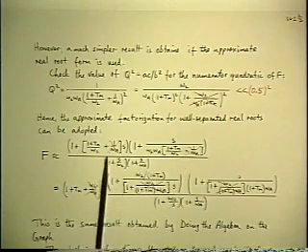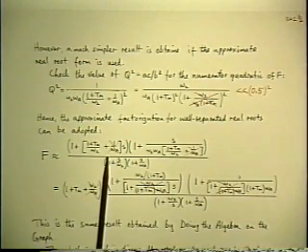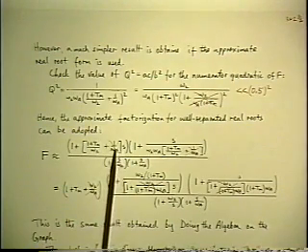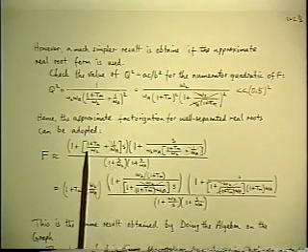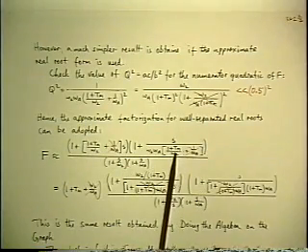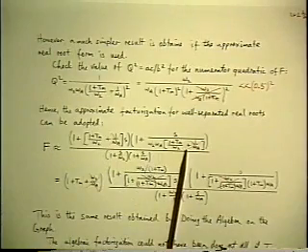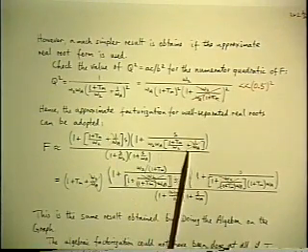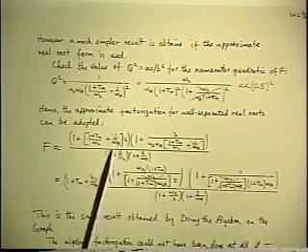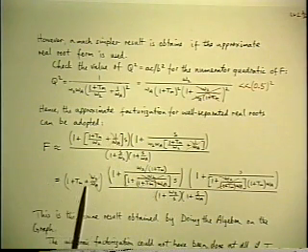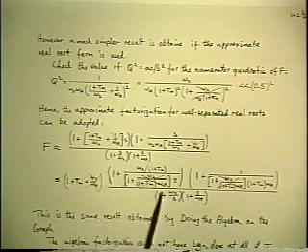But you still have a little more work to do to introduce reasonable approximations by noticing that the omega A term is negligible compared to the omega 2 term. And if you drop that out, you can reduce it down to something even simpler. And you still have to make the effort to reinvert the first pole and 0 in order to get the useful midband value as the leading coefficient.